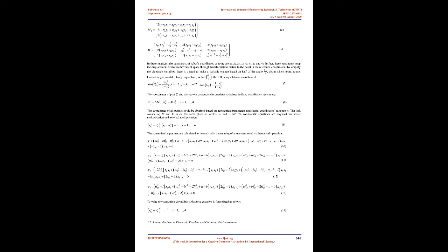However, the major problem of these robots is in the workspace of the singular points appearing in the form of unwanted vibrations. In addition, the mechanism becomes uncontrollable in singularities and incapable of tolerating the external load and torque. After obtaining the singular points based on Jacobian matrix analysis, the limit concept will be applied to the removal of singularities so that the endlessness of the transformation function when moving from Cartesian space to joint space can be prevented. In the end, the singularities of the mechanism and Jacobian matrix are computed in a general mode, following which the limit concept is used to remove these points from the PM's workspace.